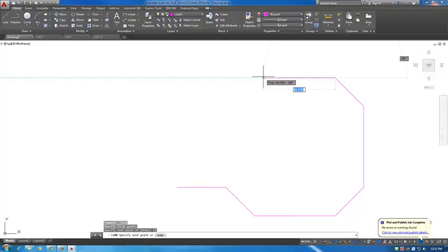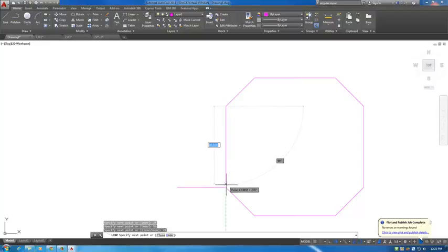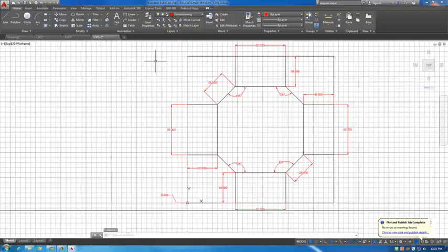Okay, another straight horizontal line. So our polar snap takes care of that for us. We'll do 50 units long. We need to do another 45-degree angle, so, or 135 I mean. 135 at 25 units long. Okay. So there's our base, our inside of this drawing. There's this drawing right here.